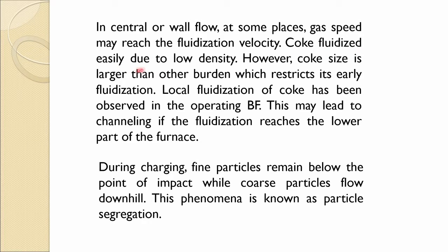Coke fluidizes easily due to its low density. However, coke size is larger than other burden, which restricts its early fluidization. Local fluidization of coke has been observed in the operating blast furnace. This may lead to channeling if the fluidization reaches the lower part of the blast furnace.